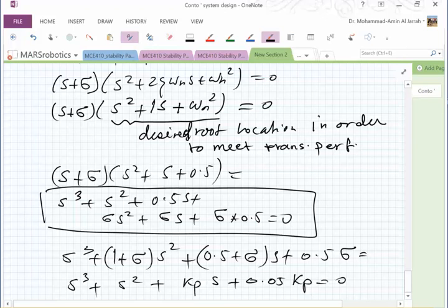This is alternative A. In alternative A, we achieved the performance with a PI. We added an integrator component to our proportional controller. So we took the error, we integrated the error over time, and we controlled the system with a quantity proportional to the accumulation of the error over time, plus a quantity proportional to the error directly.